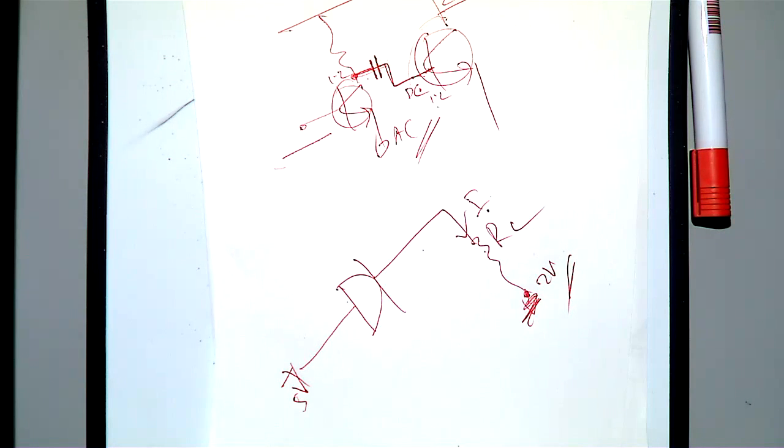So if you are using this, maybe in between you need a level shifter that will shift this voltage further down. But here the advantage is this is a PNP amplifier which will do the level shifting for you. So now here it is 6.3 volt, but here it is only 0.4 volt when you take output from here. So you don't have much problem, you are not losing the voltage swing. So that's the reason we got this stage like this. See, now you understood the importance of this stage, why we have designed this stage like this. So here we got an amplifier plus a voltage level shifter.